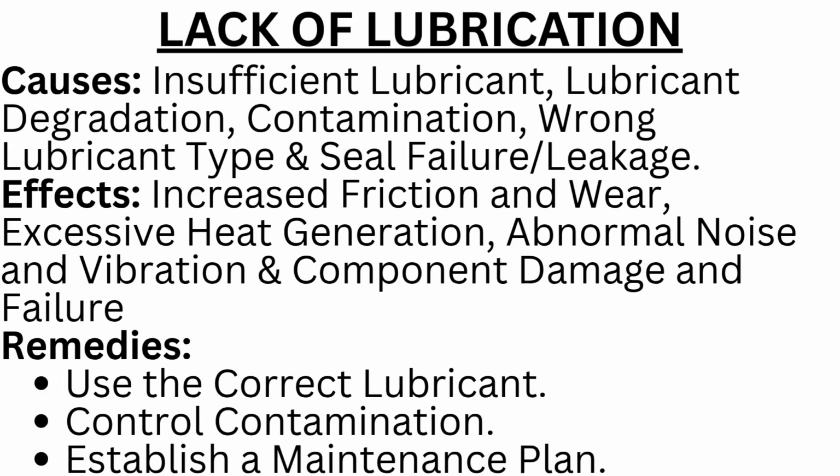Let us look at the next maintenance failure: lack of lubrication. Causes: insufficient lubricant, lubricant degradation, contamination, wrong lubricant type and seal failure or leakage. Effects: increased friction and wear, excessive heat generation, abnormal noise and vibration and component damage and failure.